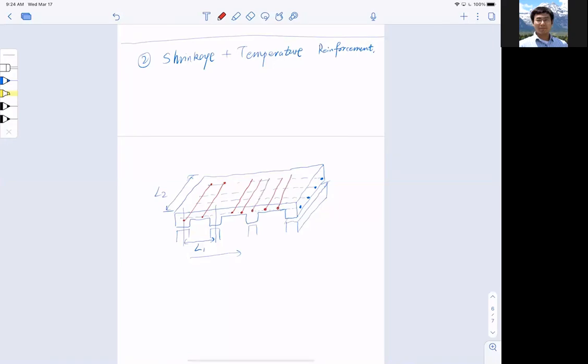This can also be treated as part of the slab, that's fine, but this is only in the slab and has nothing to do with the beam in the transverse direction. You've got to understand this. I don't want you to put bars in the bottom of that girder and say, look, Bob, that's my flexure, that's my shrinkage, and go bananas. All right, so this is the transverse direction. So now these are the shrinkage bars.